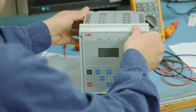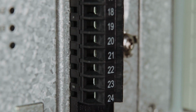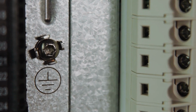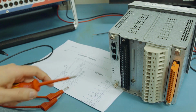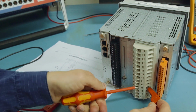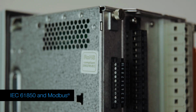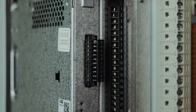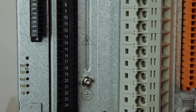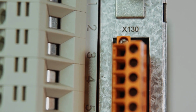All connections to the relay are made on the rear. The protective earthing screw is located on the lower part of the case. 4 different communication modules are available for wired Ethernet, fiber optic or serial communication. Supported communication protocols are IEC 61850 or Modbus, or both simultaneously. Depending on the relay variant, additional input, output, or voltage measurements can be found on the optional X130 module.